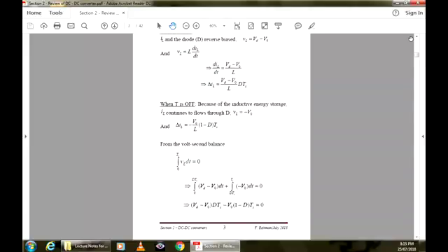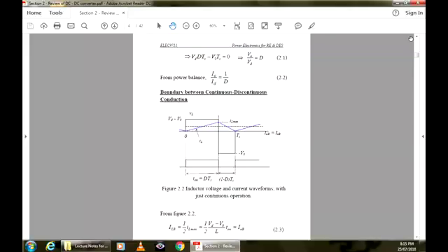So what happens at the boundary is this situation. The current starts at 0, and during DTs, the current rises at the rate (Vd minus V0) divided by L, goes to a maximum value, and then at the end of the duty cycle, it falls to 0. And then the same cycle repeats. So this is on the verge of discontinuous conduction. The load has increased to such an extent that the inductor current starts from 0 and falls to 0.